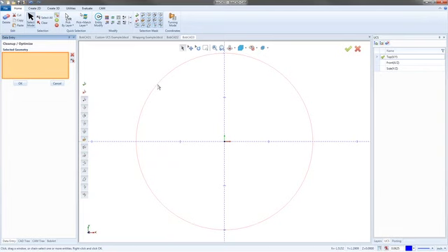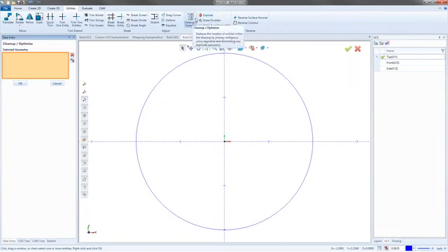It also erases doubles, which I just found out about a couple months ago. It's been longer than a couple months, probably close to a year ago. But for the longest time, I was using the utilities and doing a cleanup and optimize and an erase doubles on everything. Cleanup and optimize does erase doubles, but you'd only use erase doubles when you don't also want to rebuild the geometry. So cleanup and optimize is the function you're going to use all the time. Erase doubles is just when you think you've got duplicates. So there we go.